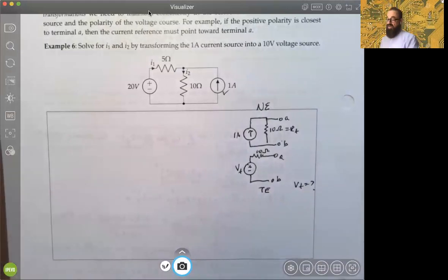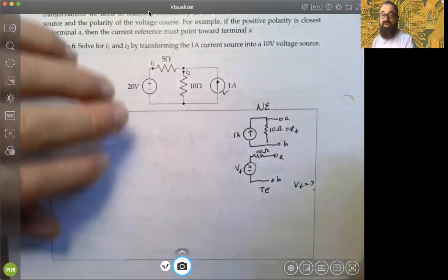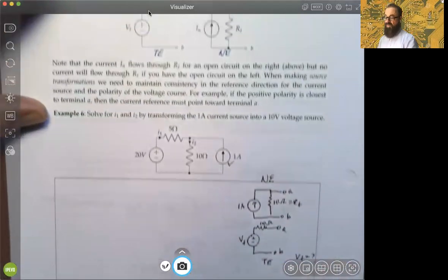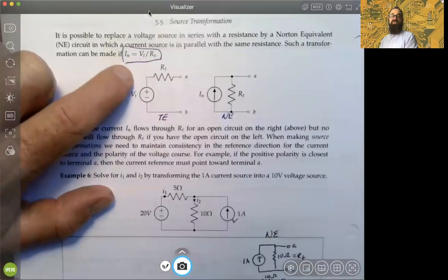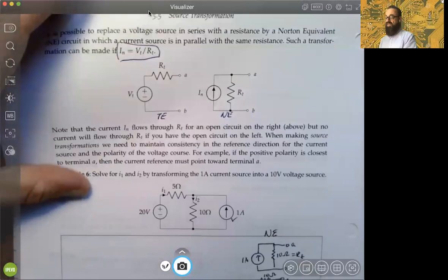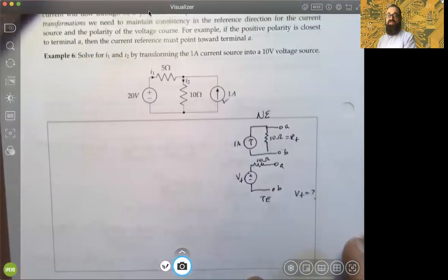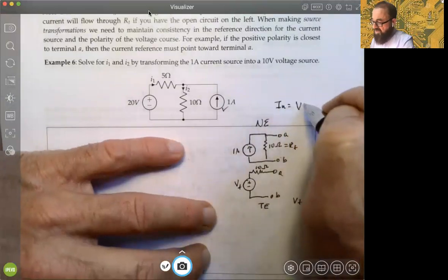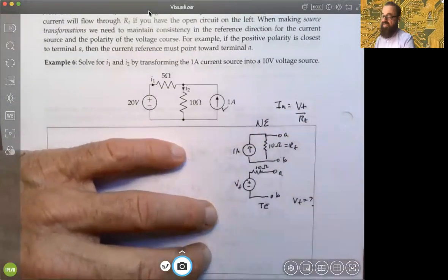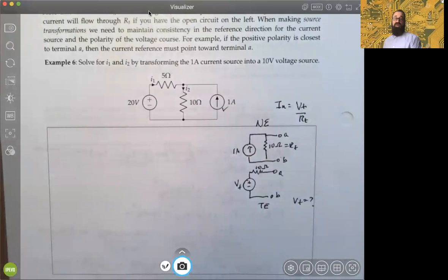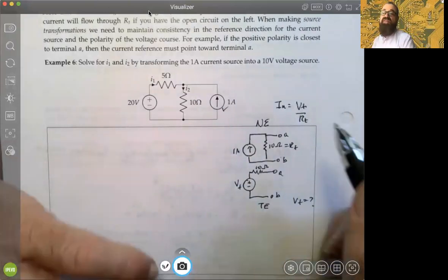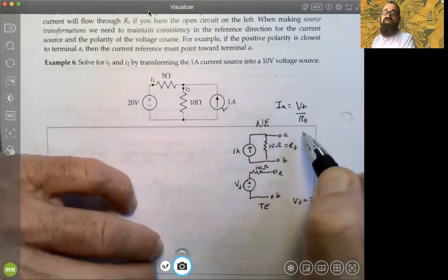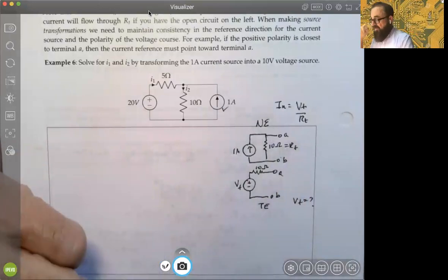Well, remember, at the top of 74, there's the equation of connection right there, and I'll write it again. So the connection is the current source of the Norton is always equal to the ratio. That's basically Ohm's law applied to these 2 equivalents. I sub n has to be the Thevenin voltage divided by the resistance, right?